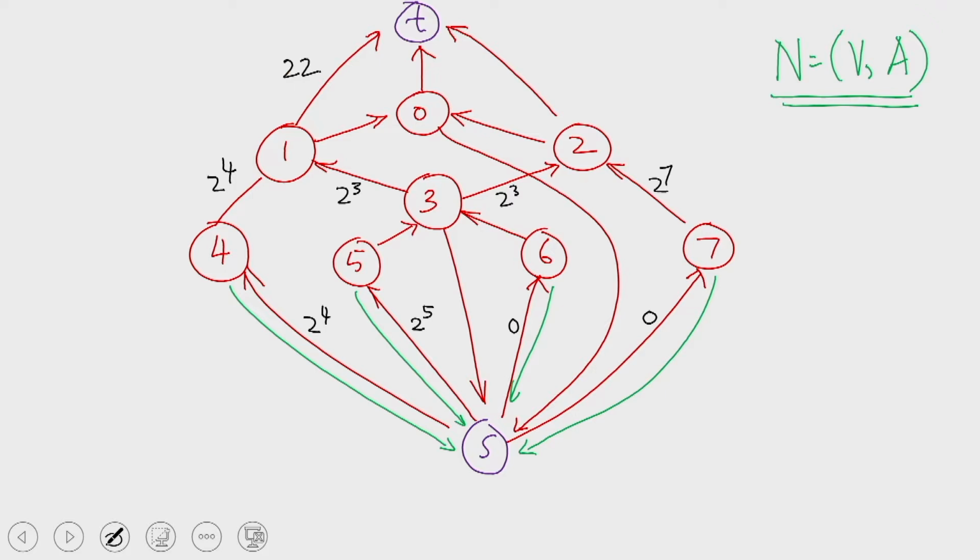Whereas for gate 2, the incoming capacity is 8 plus 128, which is 136, and there is only one input being driven by the output of gate 2, which is that of gate 0. Therefore, d equal to 1 for gate 2. So d into 2 power 2 is 4. So 136 minus 4 is 132. So the capacities of the edges involved with AND gates are marked thus.